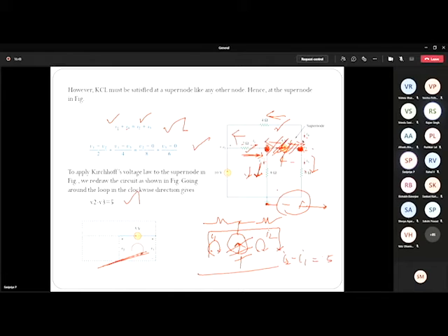You can have it on your own, but please remember when I go for a matrix method, just by inspecting the circuit, I want to write the equations. Then in those cases, you have to assume clockwise current direction for mesh analysis. For nodal analysis, you have to assume all the currents as leaving currents as far as the resistors are concerned.